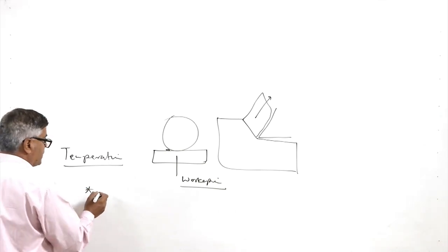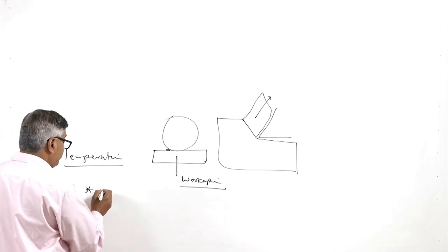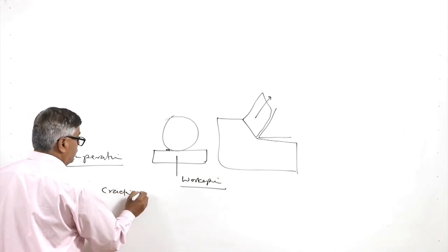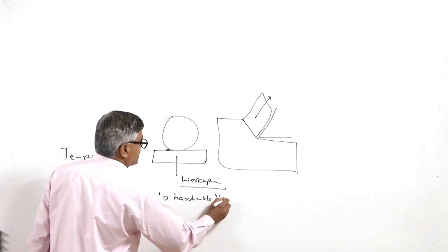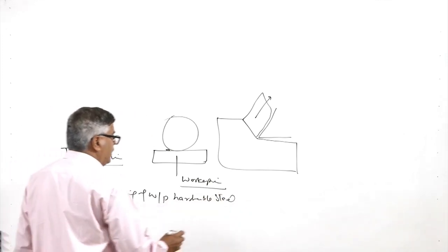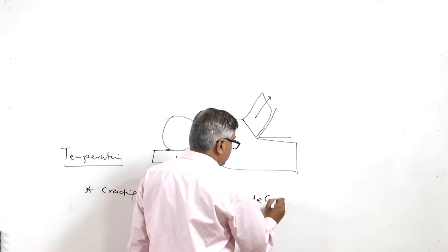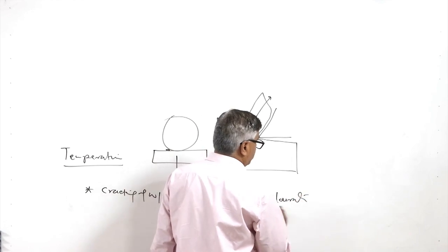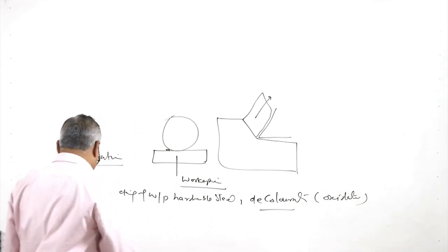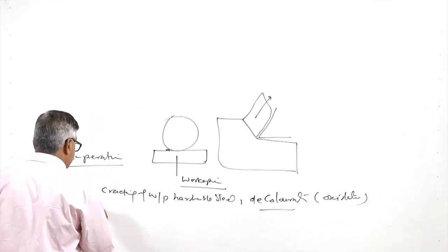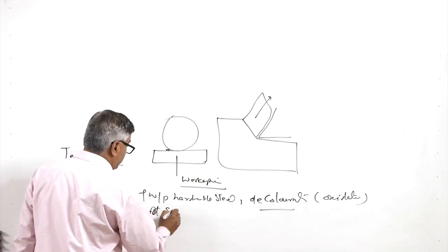And these effects appear in different forms, for example the cracking of the workpiece, which hardenable steels experience. Apart from this, there can be oxidation, which can lead to discoloration of the surface due to the oxidation of the heated metal. And there is one more, which is called burning of the material, like the formation of hard spots.